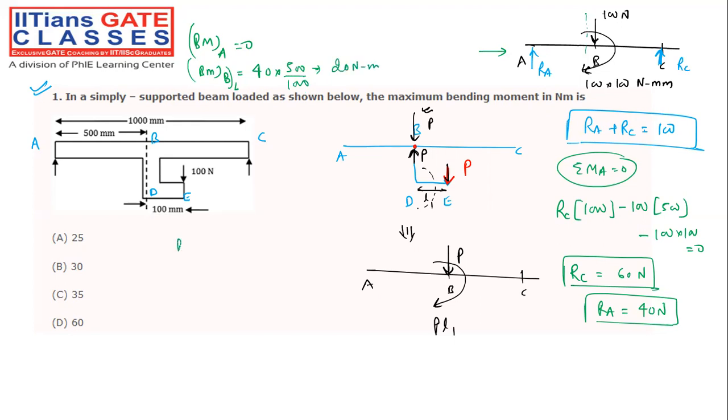What about the bending moment just to the right of B? Why are we calculating 2 times? Because there is an external moment, right? And how to decide the direction? It is also plus, it is also clockwise, in the sagging moment. So that will be added together: 20 plus 100 into 100 divided by 1000. You will be getting 30 Newton meter. What about the bending moment at point C? No need to calculate, 0.